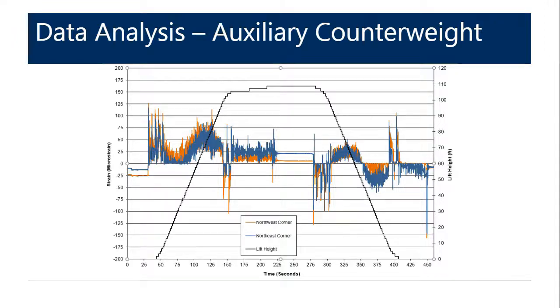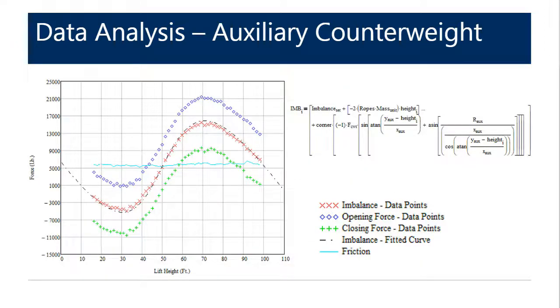Here you can see the actual data analysis and the fundamental balance equation that this data analysis relies on to enable the fitted curve to match the imbalance data and then be extrapolated to establish the seated imbalance of this particular vertical lift bridge.